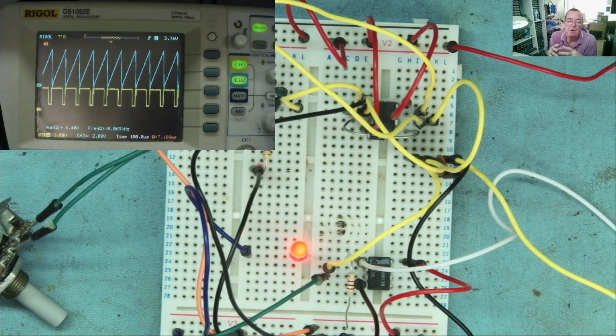But if you do have a problem with a PWM chip, it's most likely being caused again by a failure in the output devices. So if you have a MOSFET driving some sort of load, that's what's doing the grunt, the hard work, the MOSFET goes short.